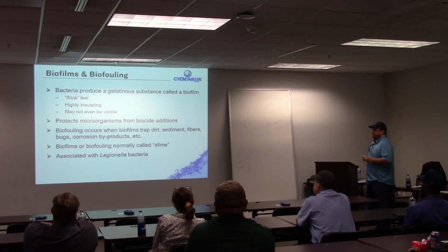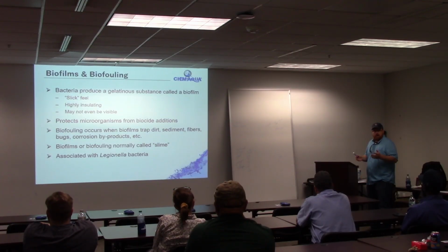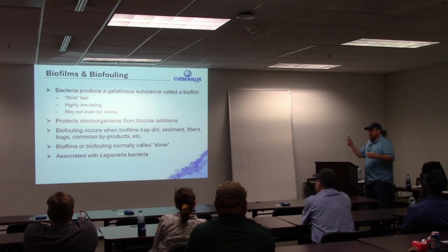It likes to live underneath existing biofilms, and that's why sometimes Legionella tests can be performed and you won't have a positive result, and literally a day later you can run a Legionella test and you might have a positive because you might have a pump that cavitated, or just the vibration from a cooling tower fan loosens a biofilm that might be present. By that biofilm loosening up a little bit, Legionella that was living within that biofilm ends up being released into the bulk water, and that can cause problems.